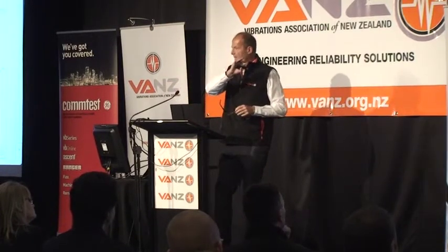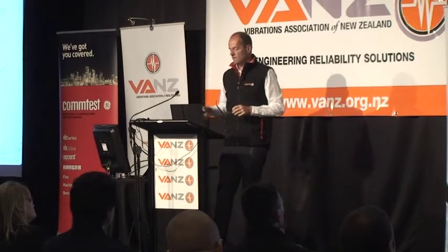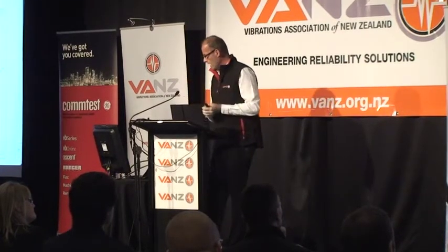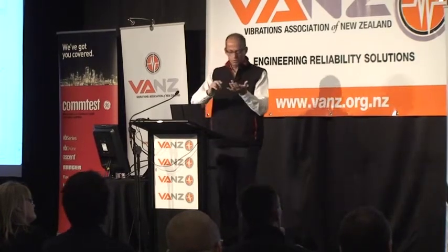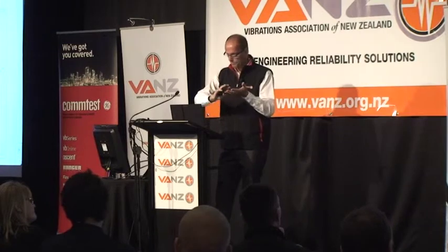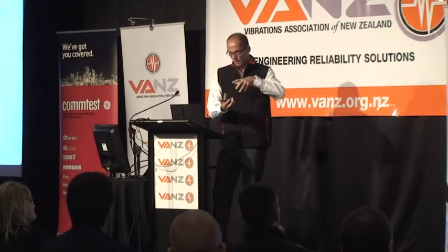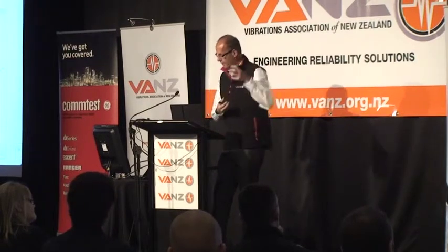But let's just say that, at some point we're running defect-free, but then at some point something happens. And we will go for a little period of time afterwards where we can't tell that there's a problem. But that problem could be because we've not aligned it properly, not balanced it properly. It's been damaged, the bearings have been damaged while they were stored on a shelf, while they were installed.